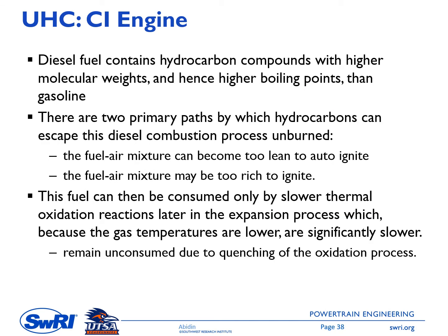For the compression ignition engine case, the diesel fuel contains hydrocarbon compounds with higher molecular weights and hence higher boiling points than gasoline. There are two primary paths by which hydrocarbon can escape the diesel combustion process. First is that the fuel-air mixture can become too lean to auto-ignite, or it can become too rich to ignite. So when we have these two conditions, the fuel can still be consumed, but by a slower thermal oxidation, and it will result in unconsumed fuel at the end.